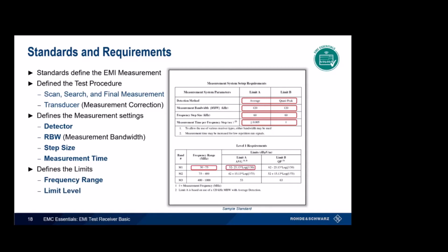One setting that is common for EMI measurement is also the use of log scales. Even the limits are written with log interpretations. Since the EMI receiver is designed to make EMI measurements, let's make a list or checklist of all the settings that we found in the standards. It would make sense that the receiver interface have direct inputs of these parameters.